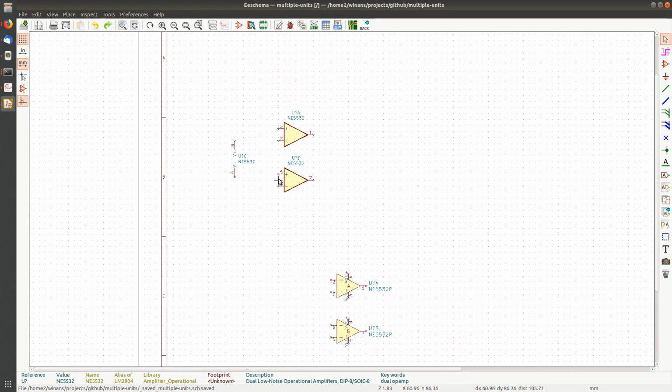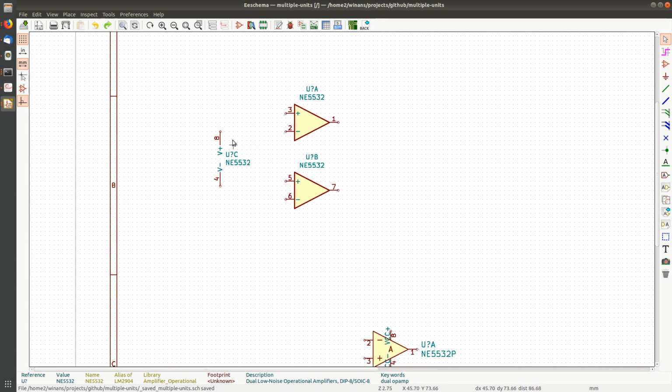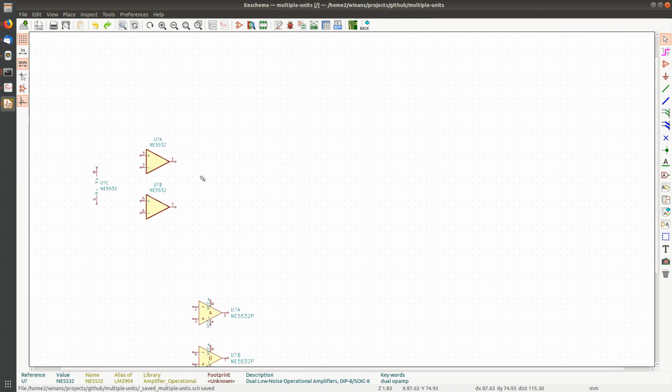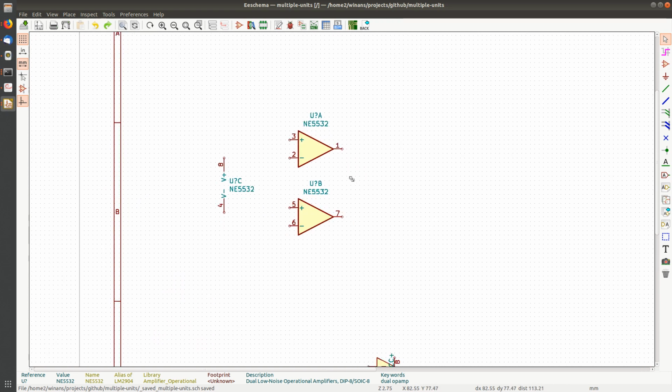All right. This one up here, what are the benefits of this design? It seems, why bother doing it this way? Well, sometimes it's nice to just put all the power in one section of your schematic. If you had 9 of these in one schematic, you could put all the 9 sets of power pins off to the side or even on its own sheet, while all of the 18 op-amps in that scenario could be strewn all over your schematic, even on multiple pages or whatever you want. And this is actually a very common way of drawing op-amps in schematics.